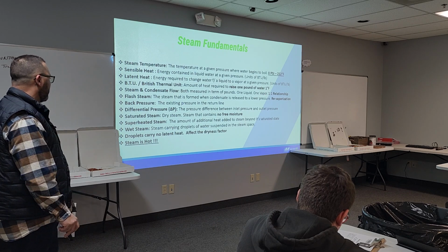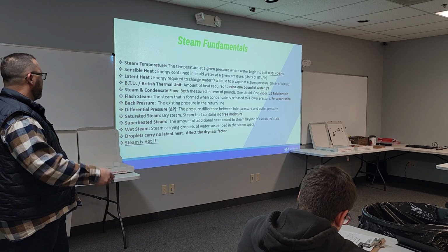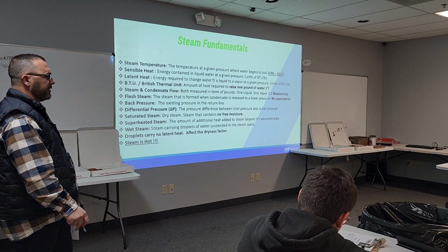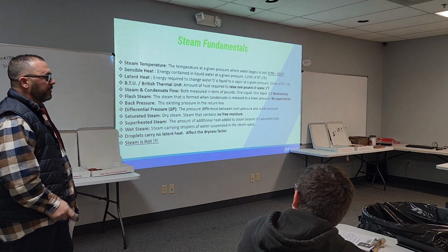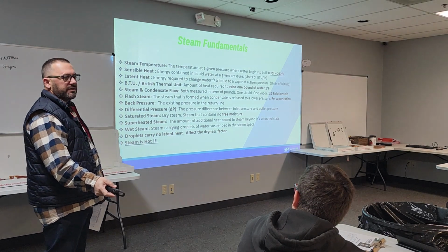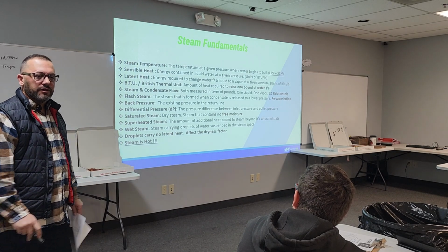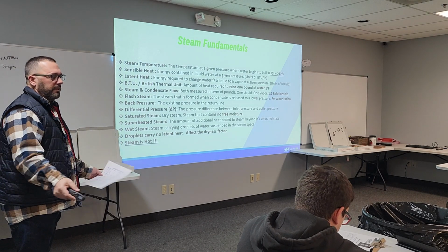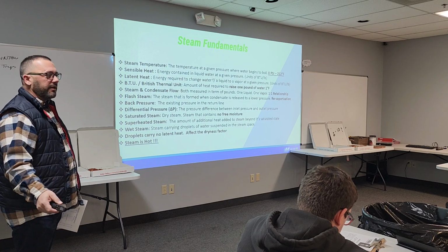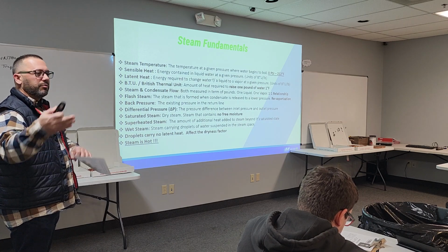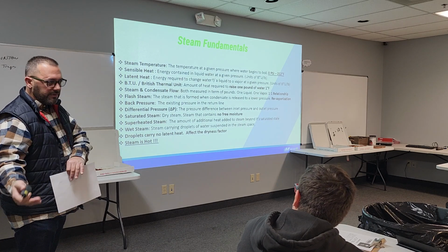Superheated steam, on the other hand, is the amount of additional heat added to steam beyond its saturated state. So, for example, Ohio State, in my backyard, their spec is 185 PSI at 585. There's not a lot of superheat, so a lot of people don't understand it, and we're not adding any additional pressure, we're adding additional temperature.